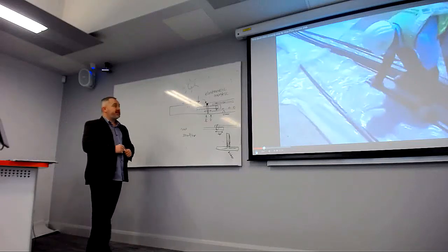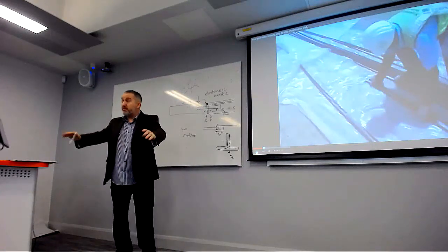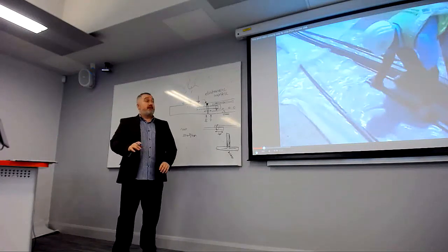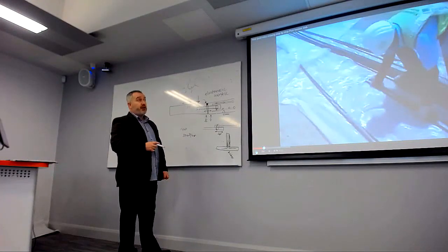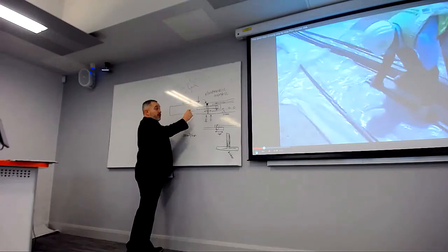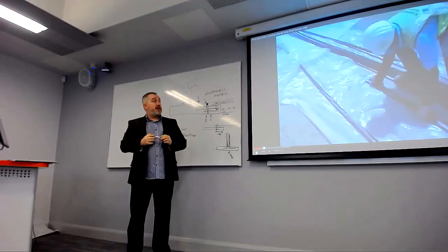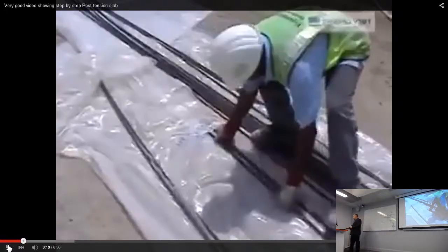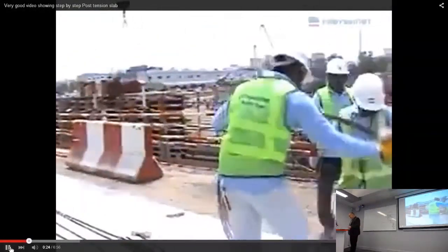Just explain what this is. So in terms of normal steel bars, you put them down and you just leave them in the concrete. What this is, is pre-tensioned or post-tensioned steel. So it's exactly the same, reinforced concrete, except the steel is stretched. And we'll look at the purpose behind that in a moment. But this is some people doing some post-tensioned concrete slabs.